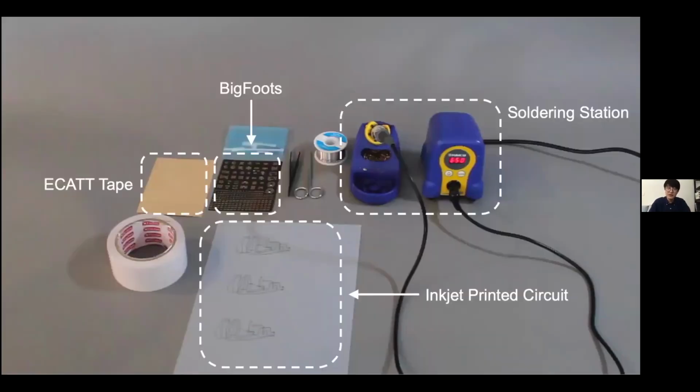As mentioned before, some of the fabrication techniques, like the Morph Sensor, work pretty nicely. However, there are still some limitations. For example, the prefabricated footprint, although quite small already, compared to bare SMD components, could still interfere with the object shape. Moreover, the circuits we're producing are more like 2.5D circuits, which limits the function design complexity and lowers the integration levels between object form and the potential functions.